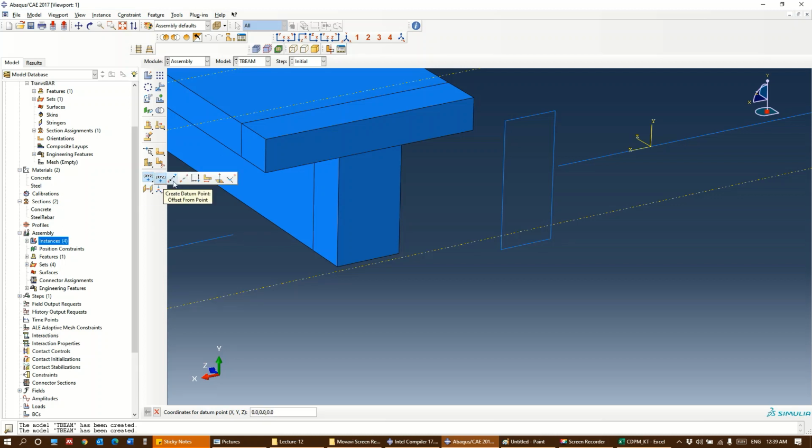Now you can see from this figure that this is based on a reference point. So this is going to be my reference point. I want this point to be on this plane at 25 in y and 25 in minus x. So it is minus 25 comma 25 comma 0. That point is created there. So all I have to do now is just select this. Done. I have to translate this from here and I'm going to drop it here.